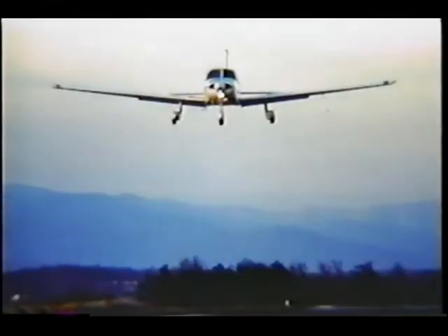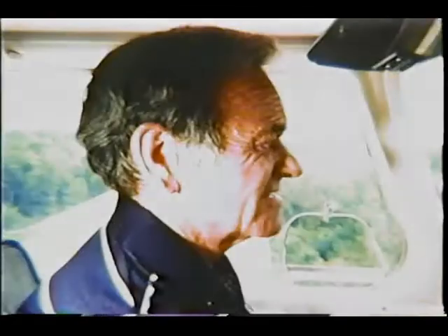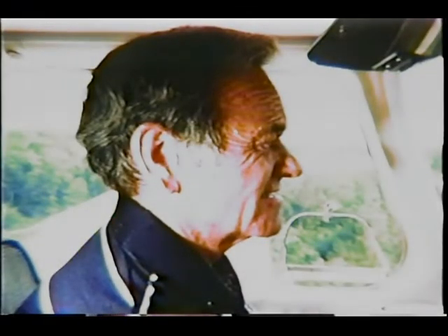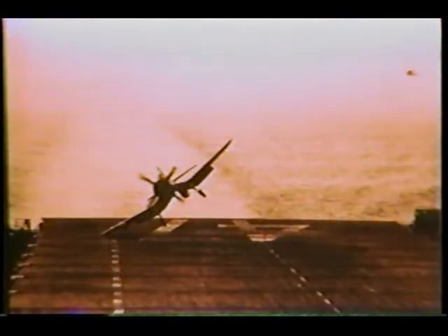If there's any question about making a safe touchdown and rollout, take the airplane around and do it early. Don't delay. Treat the go-around as a normal procedure rather than an abnormal or emergency one. World War II prop planes taking last-minute wave-offs from aircraft carriers provided those on the flight deck with some pretty spectacular maneuvering. Once again, the lesson: plan ahead.